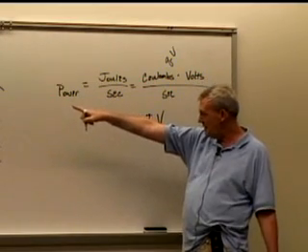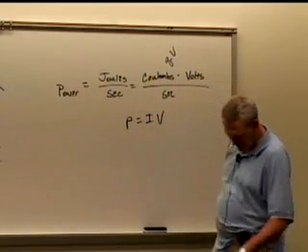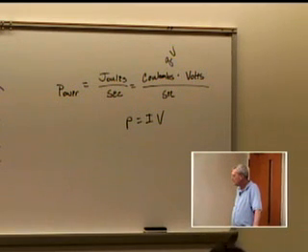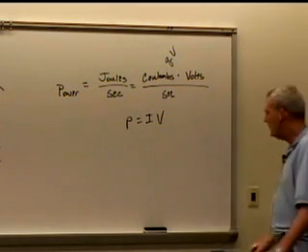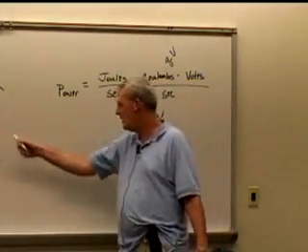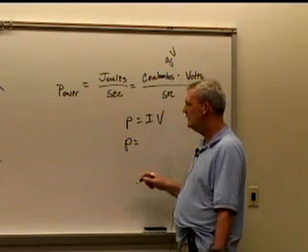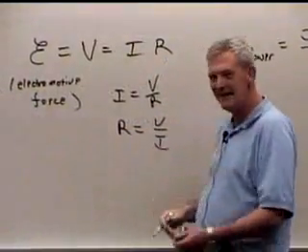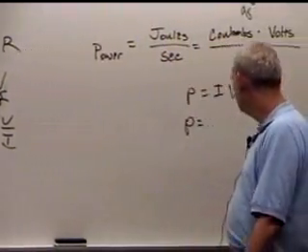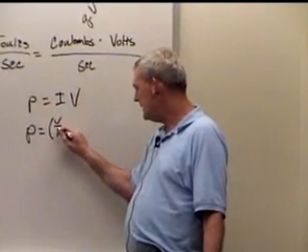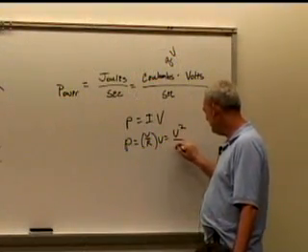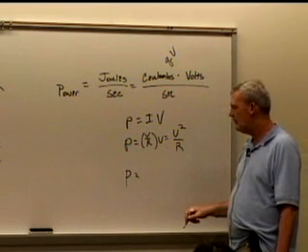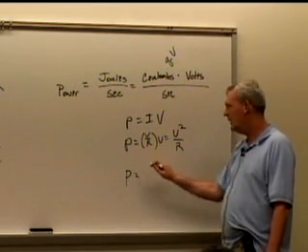So we've got V equals IR and power equals IV. And we're going to do some examples here. So we can also write power this way. Since I is equal to V over R, I can plug that V over R in here times V. And so here's a variation on the theme: V squared over R.